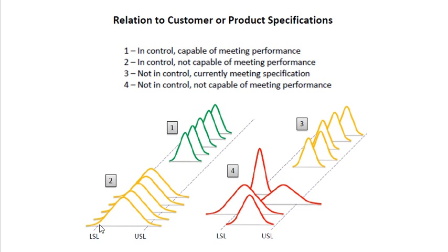within the upper and lower limits. Look at this. Here, number 2 is wider, meaning, like, the upper and lower limit. See, there's a violation, meaning your data points go above the upper and below the lower limits. Here, the process is not in control because it's shifted like that, but it's still inside the upper and lower limits. So you're still meeting the specification, but it's not that good. Here it doesn't meet the specification. Also, it isn't in control. See, it's very chaotic.